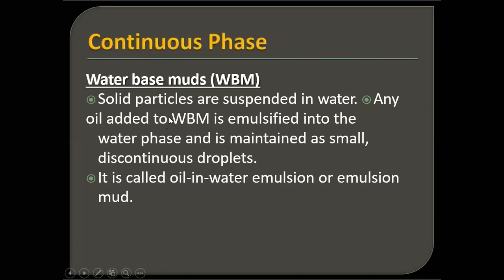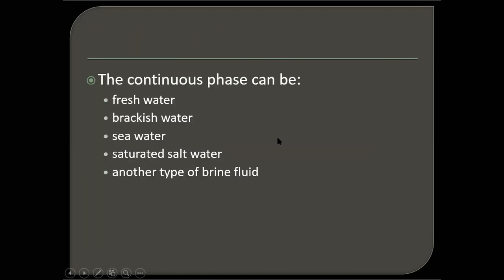For water-based mud, sometimes we put some oil in it. When some drops of oil are added to the water, it can create an emulsification or emulsion mud. This is not completely desired, but sometimes it is. But mostly we don't do that. We just use water-based or oil-based.